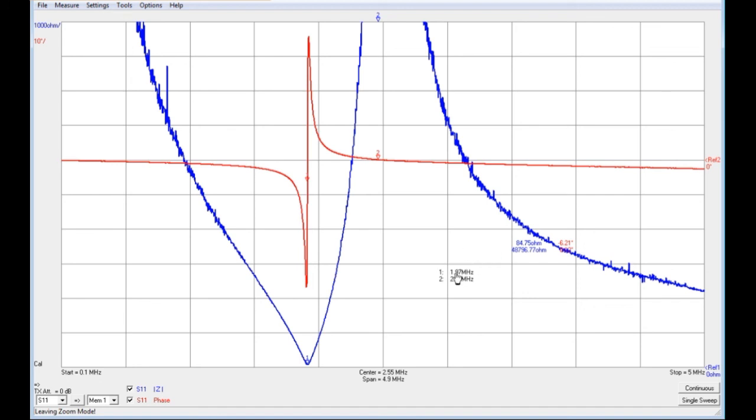And if we have a look at that, 1.97 in the 160 meter band. The 160 meter band with nominally 1.8 to 2, and we are there at 1.97 megahertz. And there's no additional wire extension on the base of that resonator or anything connected to the top end. So we're just allowing it to free resonate without any other influences, particularly the coupling of the primary.